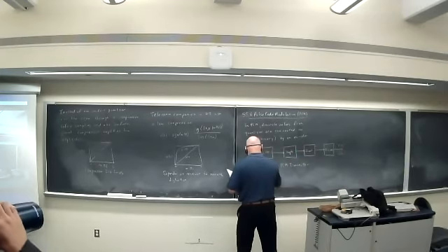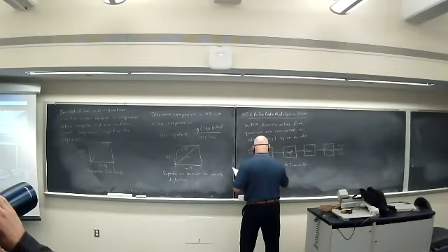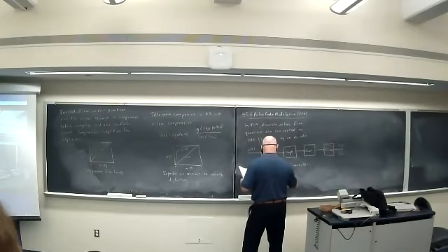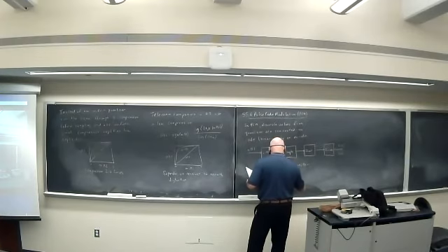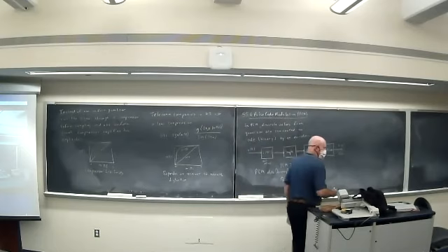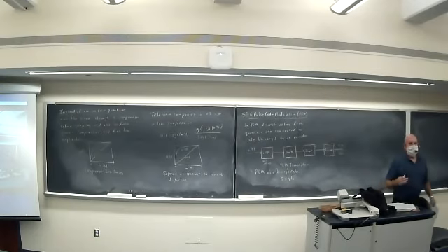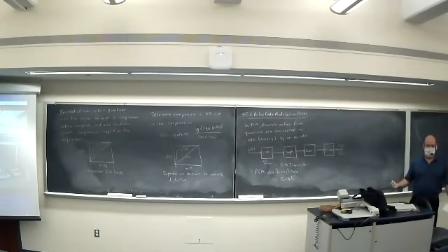Now, the pulse code modulated data rate, or binary rate, is n times my sample rate. Makes intuitive sense. If I'm taking 1,000 samples per second, that's f_s, 1,000 hertz, but I'm converting each of those samples to an 8-bit word, I need to transmit 8,000 bits per second, right?